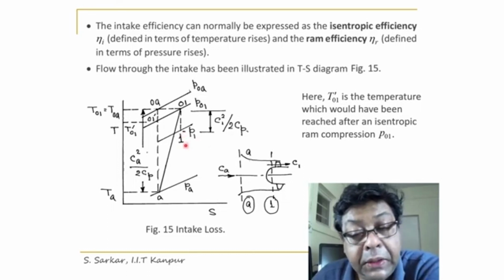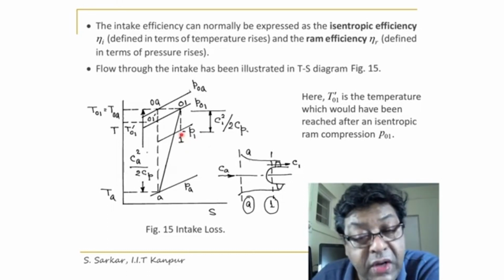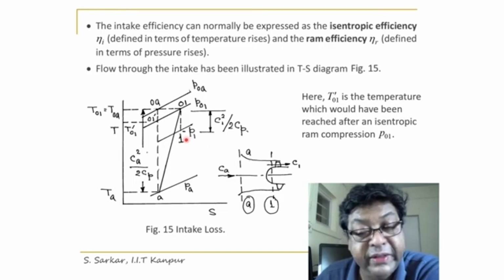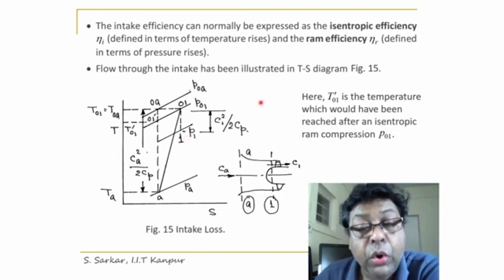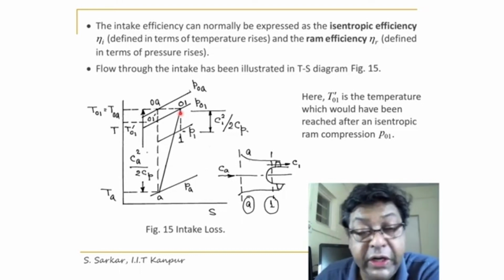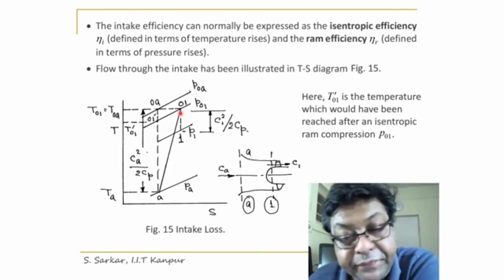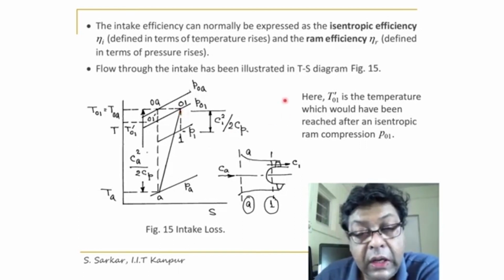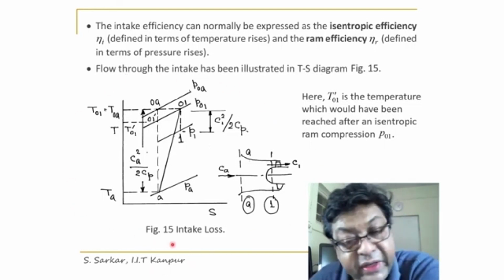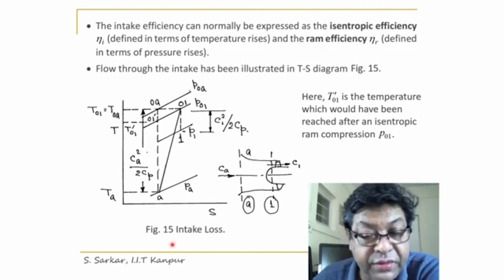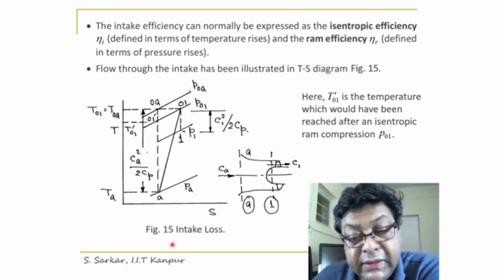and the P1 will represent the static pressure and T1 will represent the static temperature, while P01 represents the total pressure and T01 represents the total temperature. With this, one can appreciate the ram effect and thereby the pressure loss in the intake.